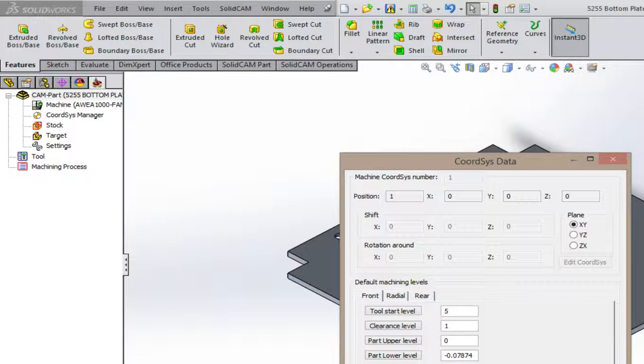Let's say on copper, we have 3 groups on copper, right? One of you is going to have to be on system G54 or machine coordinate system 1. One of you is going to have to be on G55 or 2. And one's going to have to be on G56 or 3. Because you're all going to have different origins. Those are called work coordinate systems.